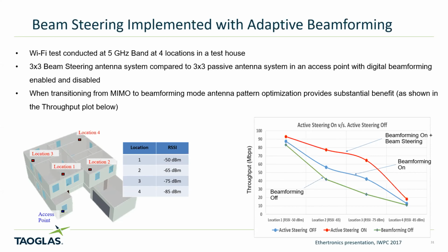That's why typically you'll see LDS type antennas in smartphones, a 3D piece of molded plastic with metallization on that plastic. So now you've got a full 3D antenna that can curve and bend and flow along different faces. But for stamped metal in a high volume application, it's very hard to beat in terms of the economics, and it is efficient because it could be anywhere from 5 to 8 mil thick, high conducting material.